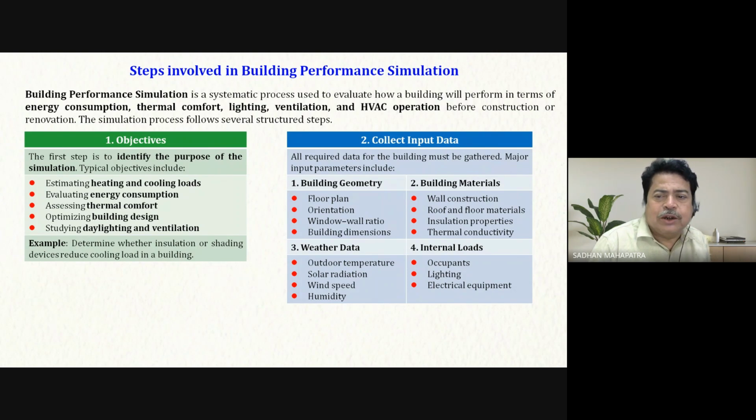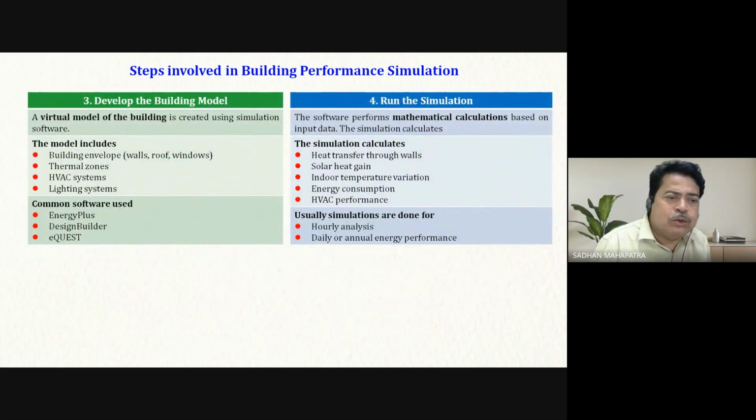You need to collect input data like building geometry, building materials, weather data, and the internal loads. Then we need to develop the building model. A virtual model of the building is created using the simulation tool. This model includes the building envelope, thermal zoning, HVAC systems, and lighting systems.